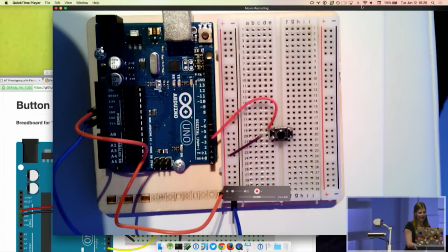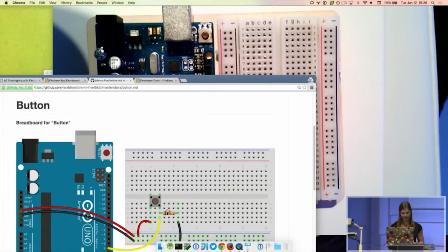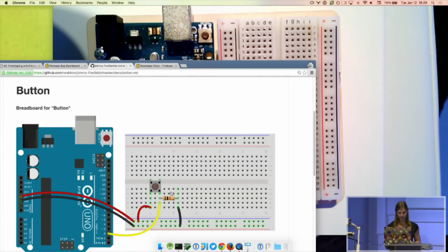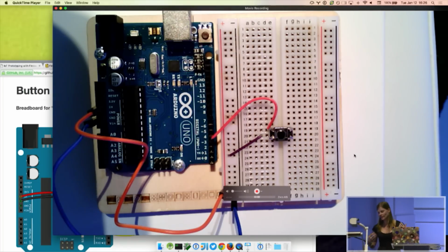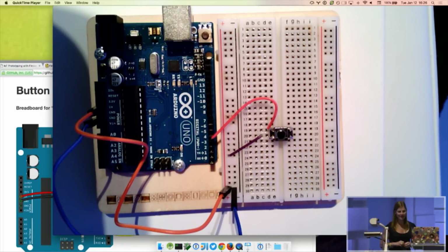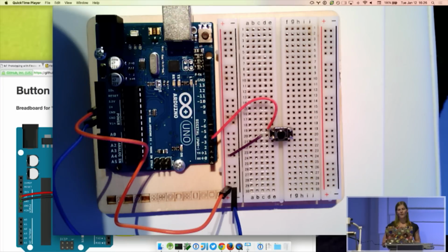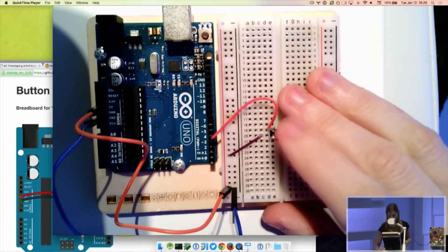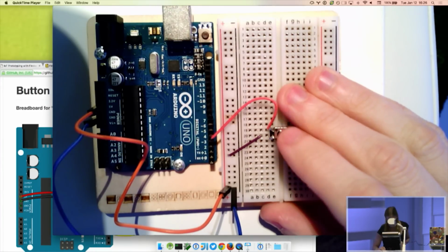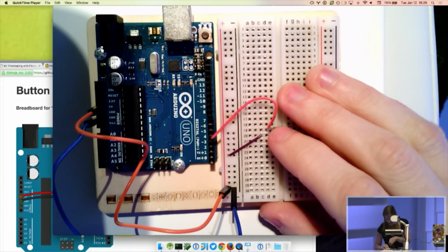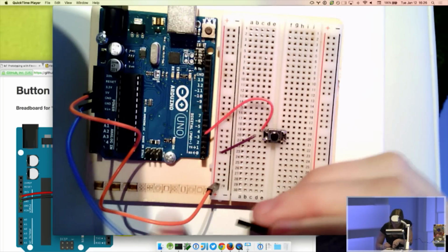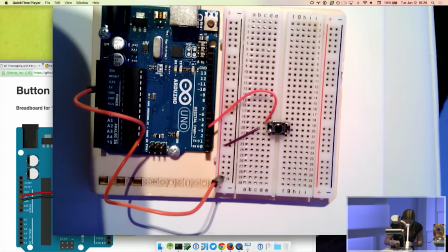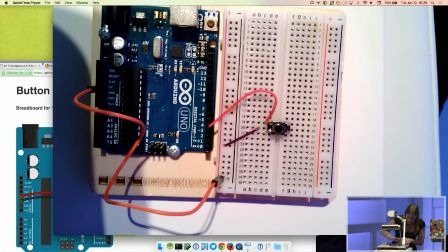But there was actually something extra in this. There was a resistor there that went to ground. And this is where that real-world physics stuff comes in. Our button copies state, but only when the button is pushed, when it's closed. So when the button is pushed, everything is fine. The 5 volt is coming across, and it's getting sent over to, oh, that jumper wire broke. I'll replace it. It sends it over to the input, and we read it.